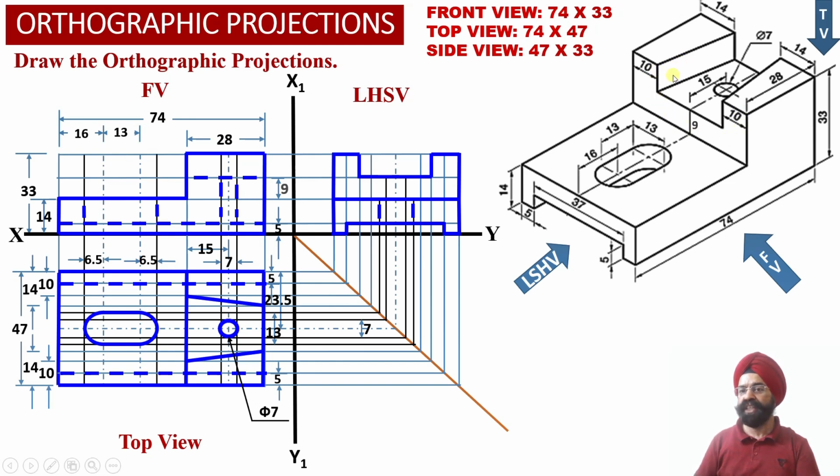But this long elongated tapered surface and this long elongated tapered surface, because of the less inclination, will be appearing as an apparent shape highly foreshortened surface onto the left hand side and onto the right hand side portion of the solid over here.